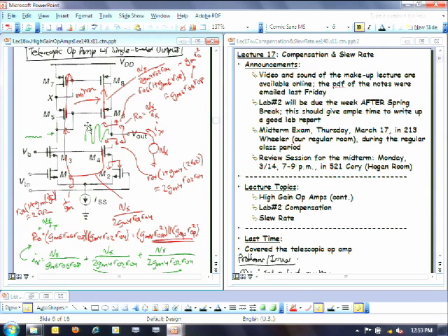It takes a lot to understand what's going on with that thing. What was going on with that problem? See, this one was not diode connected. This one was diode connected. This one was not, right? So in that problem, what you see is a very low impedance on this side here. This side shows the very high impedance here. So you, in fact, just have a current mirror going from this way to that way. It ended up being that, and you have to know what the impedance is on this side.